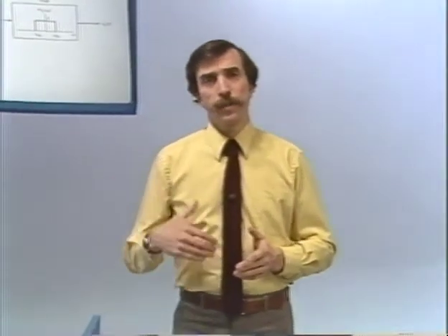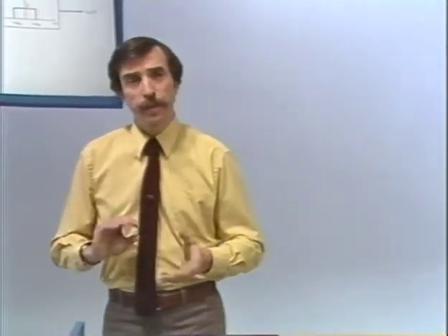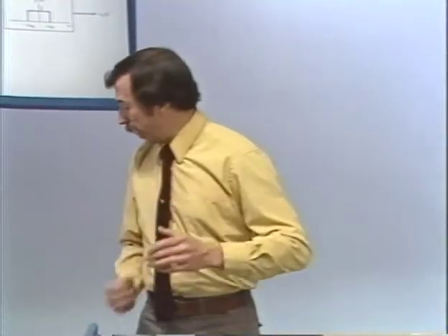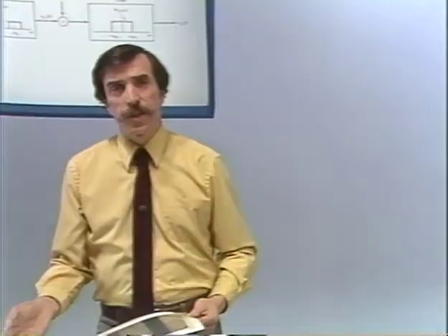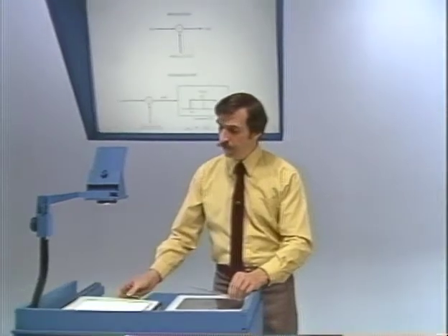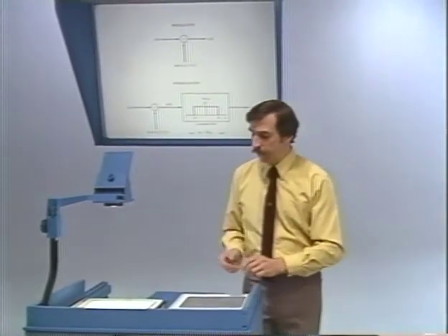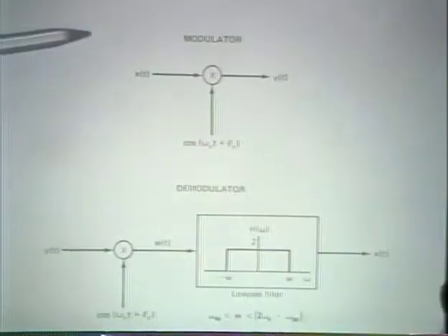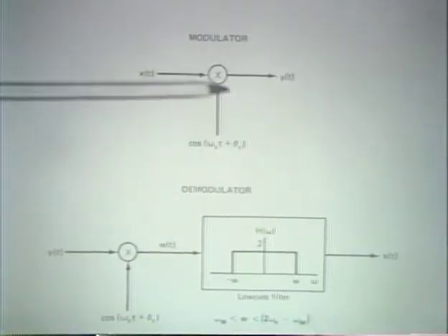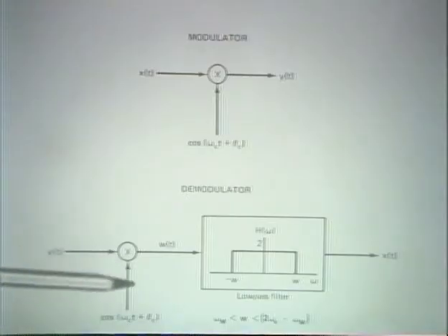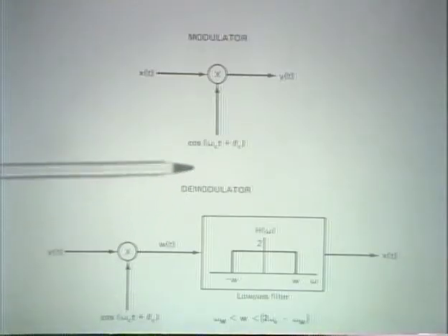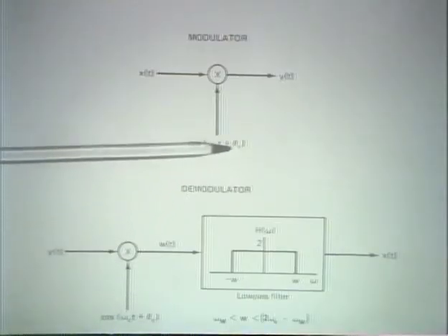And the reason for the term synchronous is that, in fact, what's implied in these systems is a synchronization between the transmitter and receiver. In particular, in the system, as we've talked about it, the modulator and the demodulator have a synchronization in both frequency and phase.